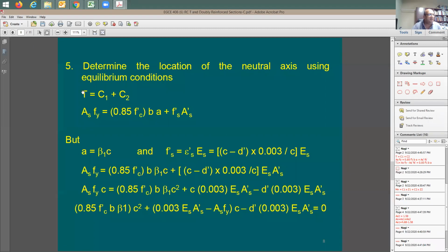This here it says the tension steel is yielding. Compression number one, C1 is equal to 0.85 F prime C b a. It's going to be compression in the concrete. And compression in the steel is going to be based on this random Fs prime that I don't have the exact value for. Now, let me put here in boxes the available information and the unknowns. I'm going to say all of this information is going to be available to you. Am I correct?